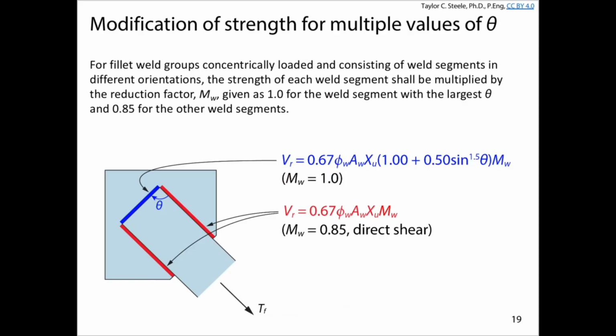So let's just say they're installing this in the field in a similar manner as the flat bar in that school across the river. We're going to field weld this. That means we need to have fillet weld sizes in a single pass no bigger than 6 millimeters. We can build them up to be bigger using 6 millimeter welds to make 8 or 12 or whatever, but the maximum single pass weld size will be 6. What else do we need to decide?